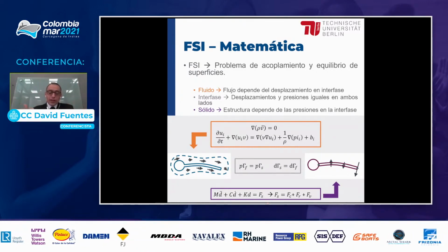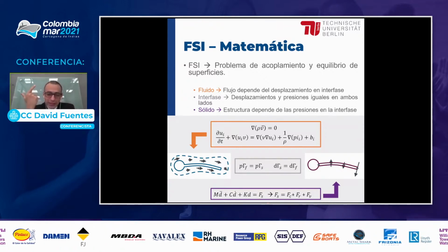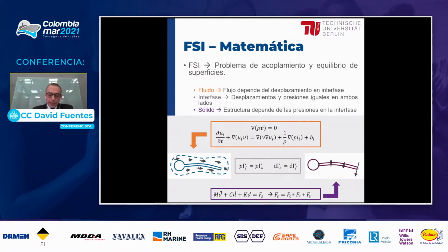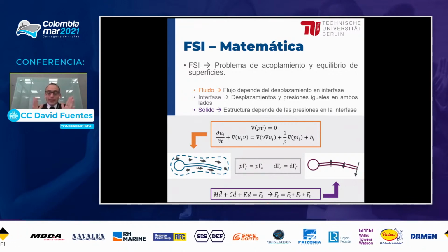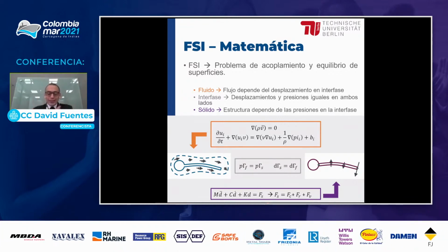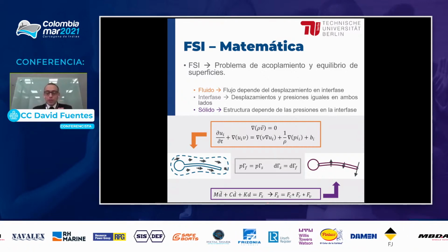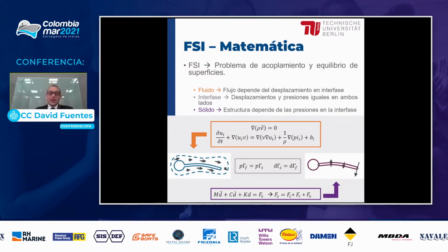And this equation for the structural component contains the mass and matrix of the rigid edge, and for the model it also considers the effects of the hydrodynamic mass and hydrodynamic spring. So, it is the balance between the displacement. Looking for the balance between pressures on both sides.